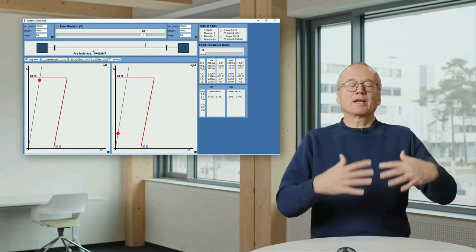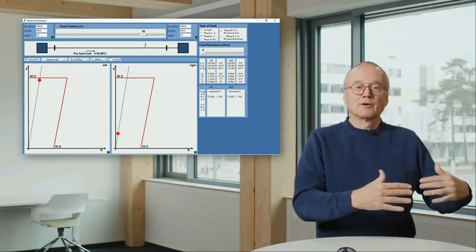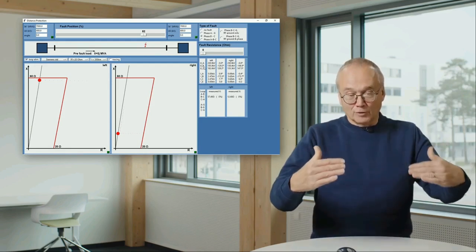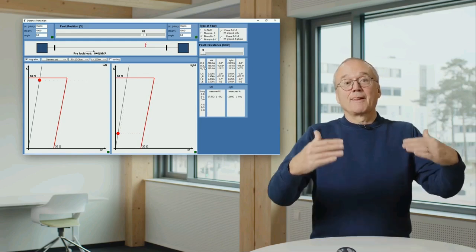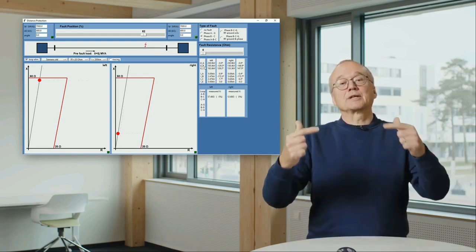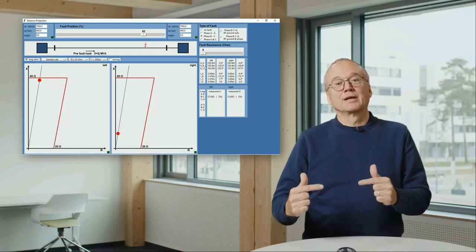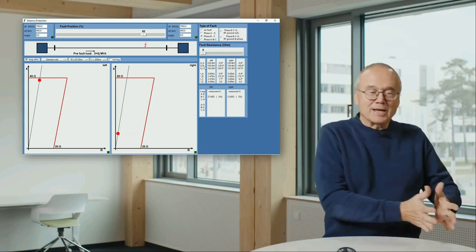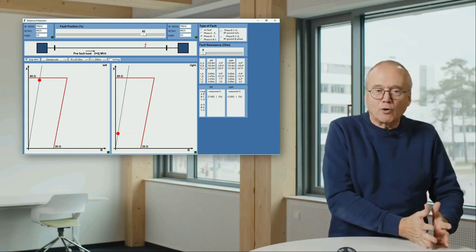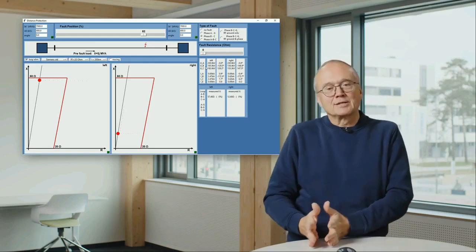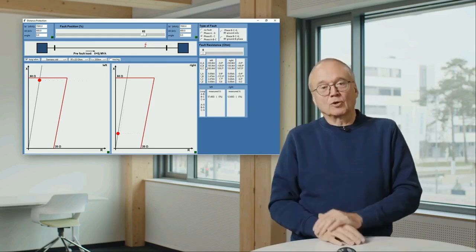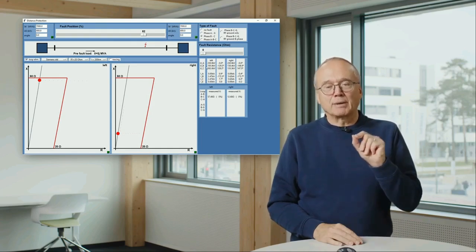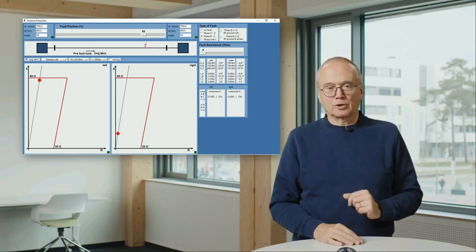And that means if we have a power flow on the line before the short circuit occurs, the voltage phase angles are different. If the voltage phase angles are different, during the short circuit, the current phase angles are different, and that causes problems. That means there is a relation between pre-fault load flow and the movement of our impedance measurement. And I will also show that in the simulation by activating a pre-fault load flow.